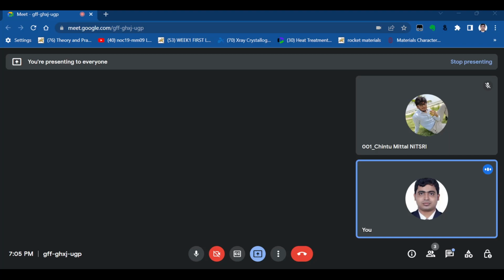So that's why I use this equation by 2. When this 2 goes to this side, this becomes our yield stress. So you can directly write sigma max minus sigma min equal to sigma ys. This is one form for Tresca. Also you can write (sigma max minus sigma min) by 2 equal to tau max.